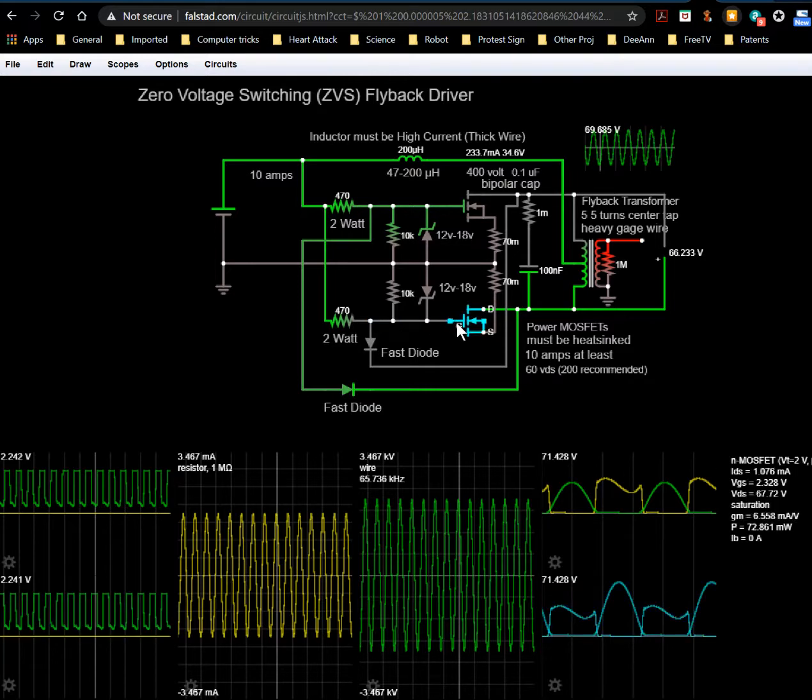Because this gate, if you know anything about FETs, this particular FET is an N-channel FET, it's got to be high, in other words, a higher voltage than ground, at its source or whatever. But basically, you got the VCC, in this case a 12-volt battery, or 24-volt in this case.